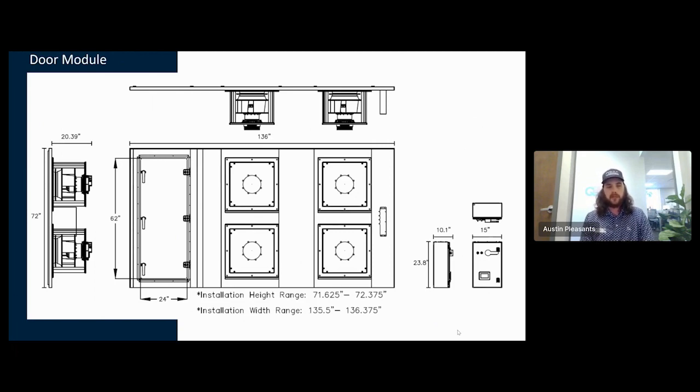It just provides a lot more flexibility. If you have the space in the Airstream to do a door in the bulkhead wall, I highly recommend it. It can really come in handy. We usually try to size the width of the door to be at least the depth of each plug fan, so that way you can pull one of the fans through the door if you need to replace it. But I know a lot of people really like these doors and have a lot of different use cases for it. So I highly recommend throwing it on as a special request if you have the room for it.